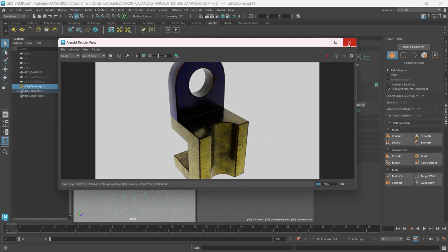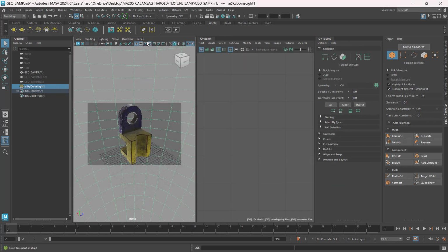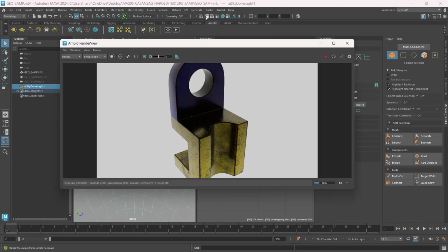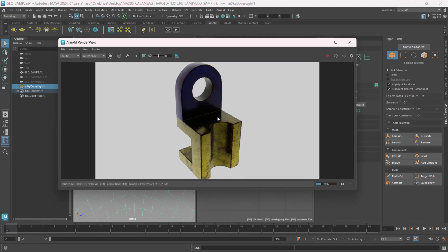So now, see that, but still there's a cropping. So I can click this. So that is the apple size. Or this. Then I'll just right click and then drag. And then from here, I'll just render once more. There. So as you can see, the material that we have created is now affecting the object.